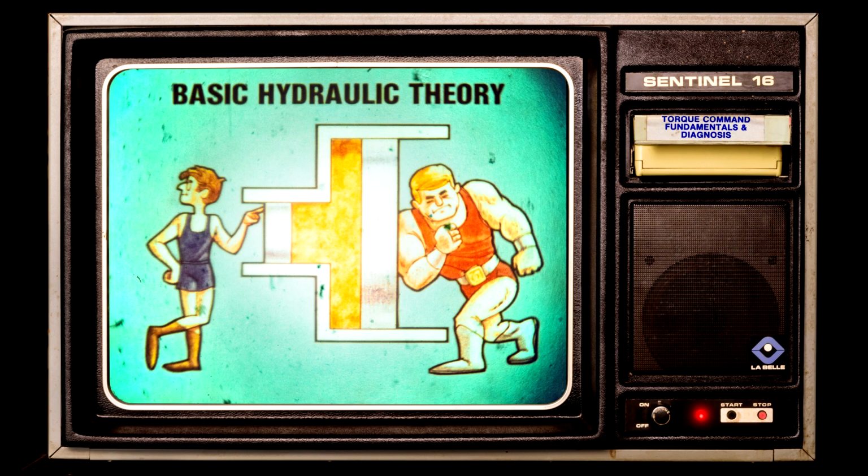In Torque Command, hydraulics principles are used to do several important things. Hydraulic fluid will transmit torque, operate valves and servos to apply clutches and bands, as well as lubricate the transmission and provide cooling. Hydraulics are the primary means of automatically engaging various transmission gears. Let's take a look at how hydraulic principles make an automatic transmission possible.